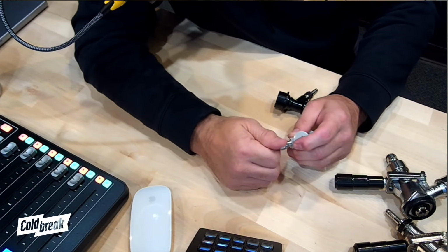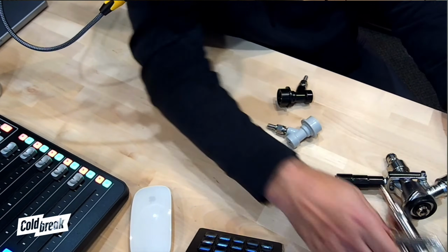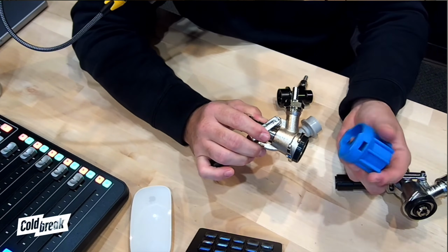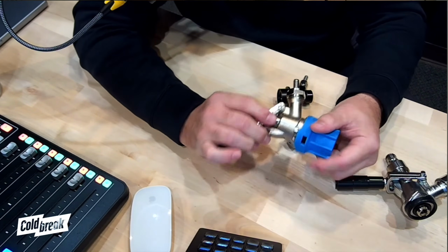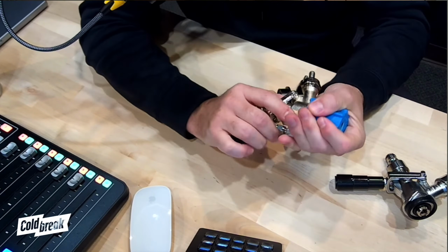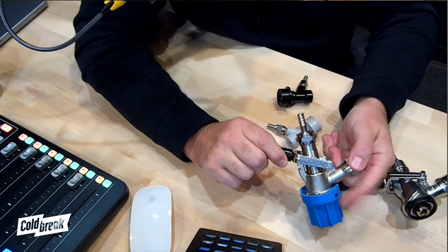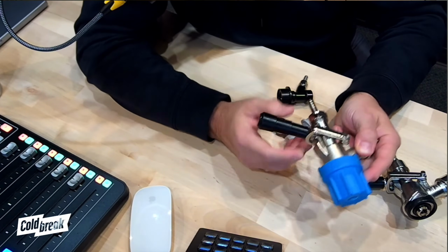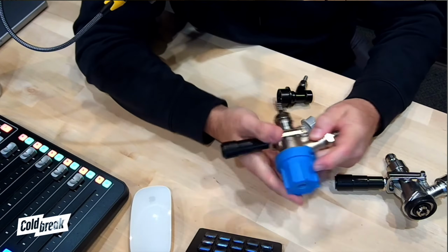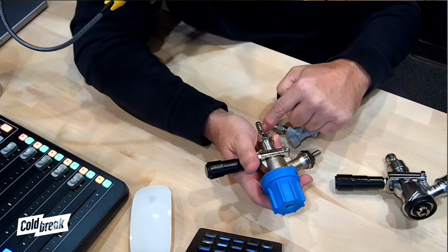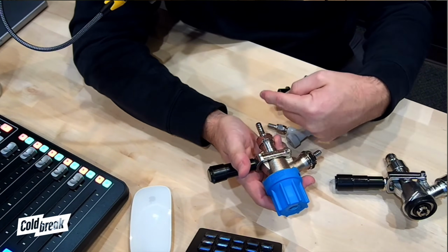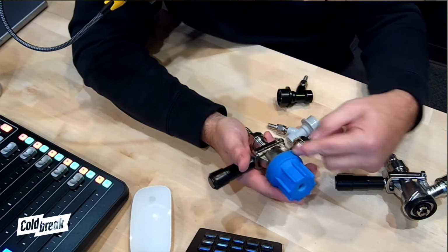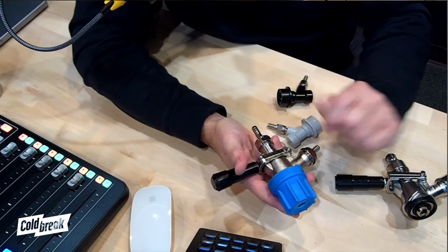So, one easy way to keep your couplers clean is these coupler cleaning caps. We'll get into this when we actually do the cleaning part at the end of tomorrow, but these just lock onto your Sankey D couplers. It keeps them clean if you're out in the field, but also at the end of the day, you can untap your keg and engage this, and it makes a connection between your gas and your liquid and will force gas through your system. If you're using a jockey box, it will purge your system this way, just by connecting and closing this off.